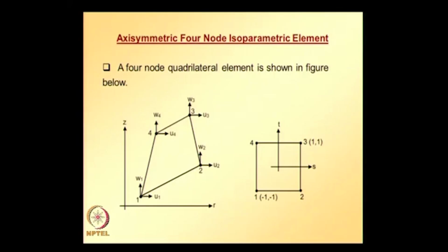That parent element looks similar to what we used for plane stress plane strain problems, a 4 node parent element with all the 4 nodes at the 4 vertices of a square. The coordinates of each of the nodes are also indicated in the figure.